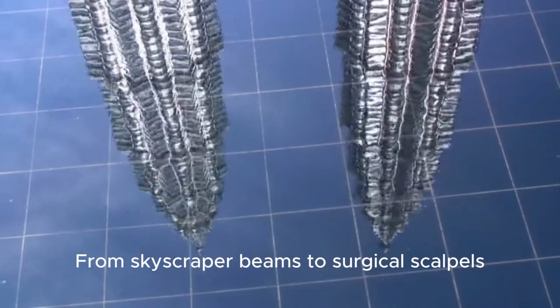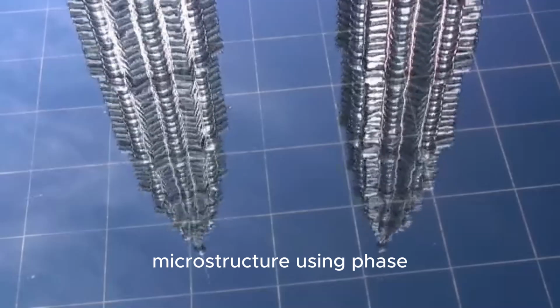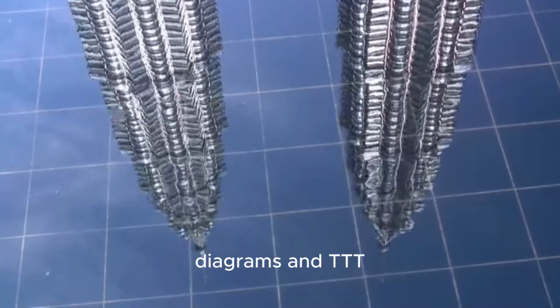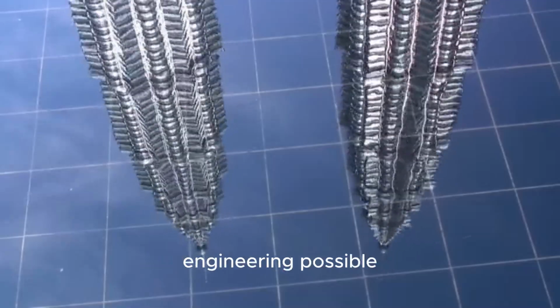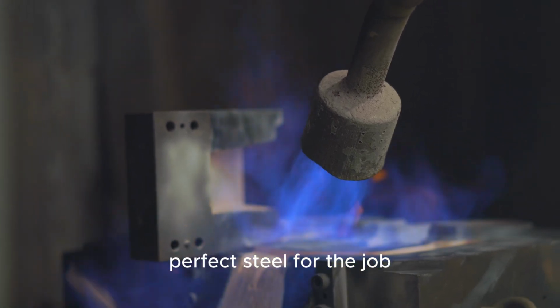It's from skyscraper beams to surgical scalpels. The ability to control steel's microstructure using phase diagrams and TTT curves is what makes modern engineering possible. It's all about controlling the heat and the time to cook up the perfect steel for the job.